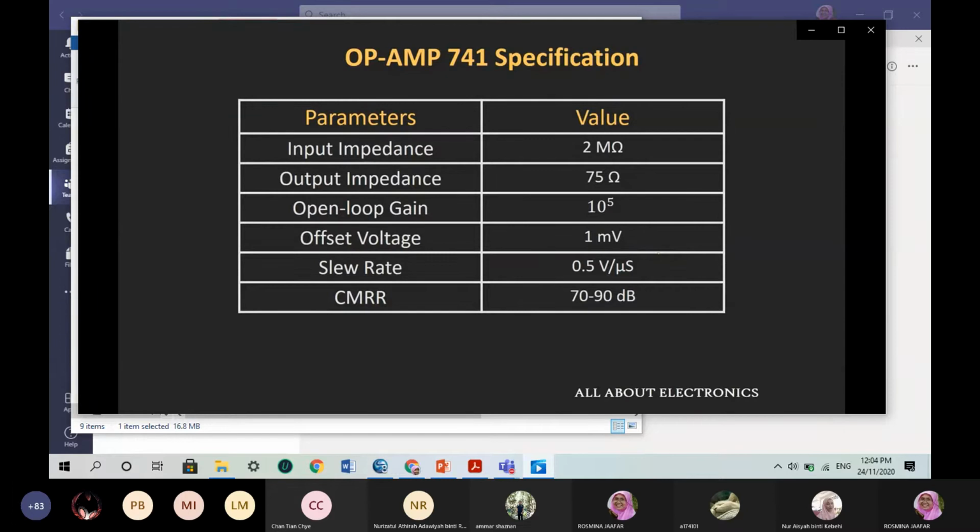So now if you see the different op-amp ICs, they are optimized for different parameters. Let's say one op-amp is optimized for a very high slew rate, while another op-amp is optimized for a very high open loop gain. And if you see some other IC, you might find that it is optimized for very low offset voltages. So depending upon your application, you need to decide which parameter is critical for your application, and based on that you can decide which op-amp is suitable for your particular application.